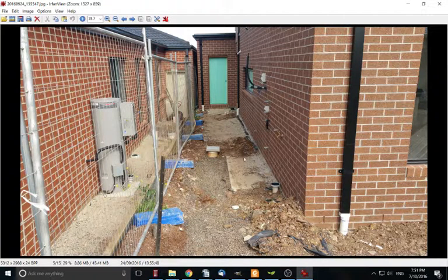And there's a slab here they put in for the hot water service and air conditioning. It's probably too low, and a common thing that happens nowadays is that they're put in as part of the contract of the house, and the hot water service and the air conditioner usually turn out to be too low. So a general tip is to see if you can get them to put them up high, so the air conditioners can mount on brackets on walls nowadays. That's a good way of doing it.